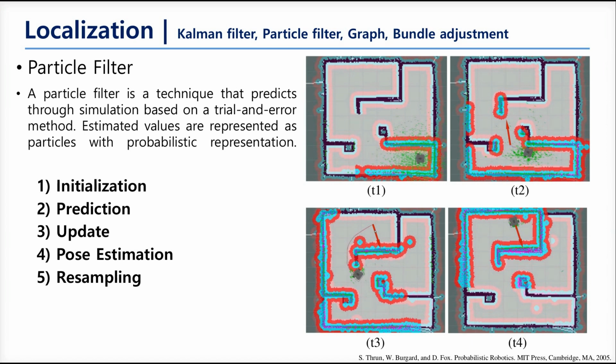In the initialization, particles spread to the randomized field, and then, during the move of the robot, it gathers the data seen from the various states of the object, and the particles converge to a specific point. If the particles converge to nearby a single point on the map, that means the robot is now placed in that location with high probability.